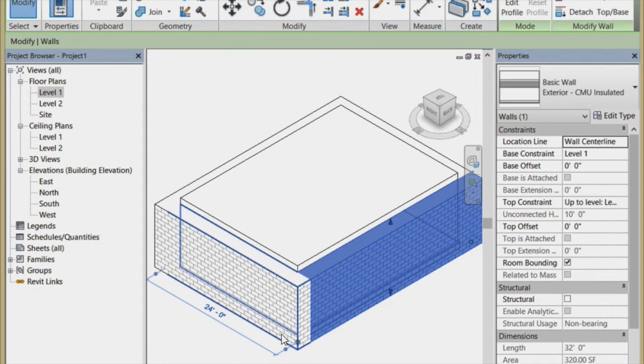Based on what I told you right now, there seems to be this notion of making it higher. It often has to do with the amount of roof surface there is on the building and how heat's trying to rise and go out through that direction. Often we try to make it higher. If nothing else, it should at least be as good. It makes no sense to have a roof which is very poorly insulated and walls that are very strongly insulated, because then your system's only as good as your weakest link.